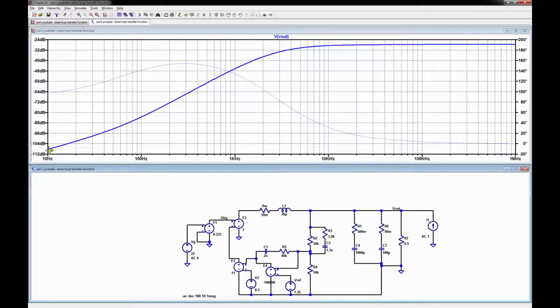And look what we have. This here is really the output impedance. Why? Because this is an AC current of 1. So a voltage divided by 1 is the output impedance. That's why this represents the output impedance as well. Why? Because what does this do? It gives me this divided by this, which is impedance, because that's the AC. So you could see, if you compare it again, that's exactly what we got before.